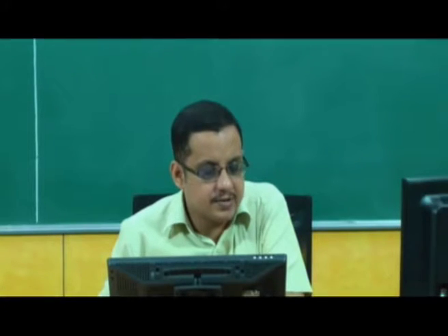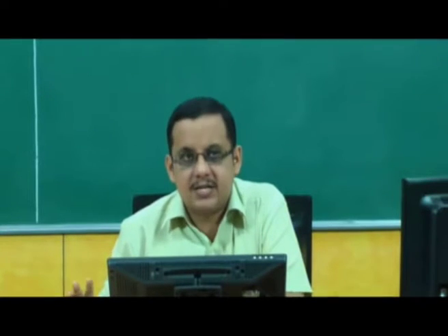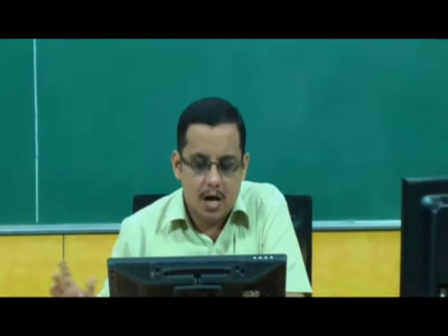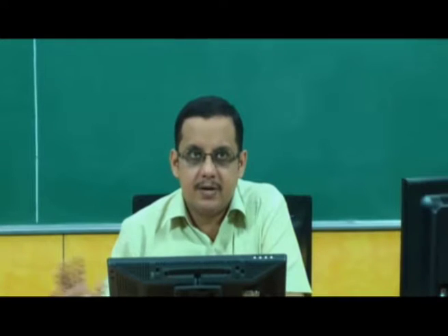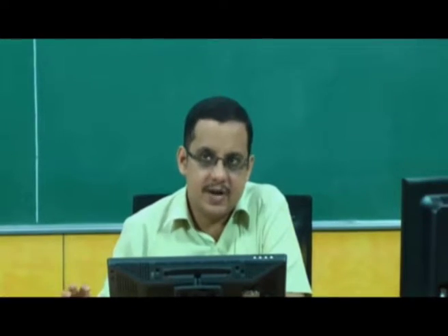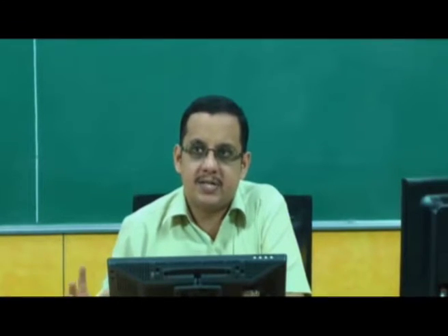KECP is asking the next question on gear train. We'll come to gear train probably in the next session, but just to give you a quick answer, a gear train is a collection of gears. Sometimes you will not be able to achieve the required gear ratio simply by using one gear pair, because that would mean that one of your gears is very large and very bulky. If you have a large bulky gear, that means it's a large mass.